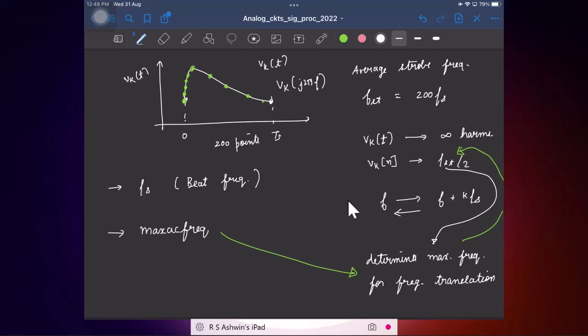And of course, this is a periodic signal, and the spectrum will have, in principle, infinite harmonics. So if you want to look at the spectrum till some harmonic, say 50 or something, you need to tell the simulator, please compute the spectrum till so many harmonics for me. That's what is relevant if you are only interested in the steady state waveforms, and that can be specified using a parameter, the number of harmonics.